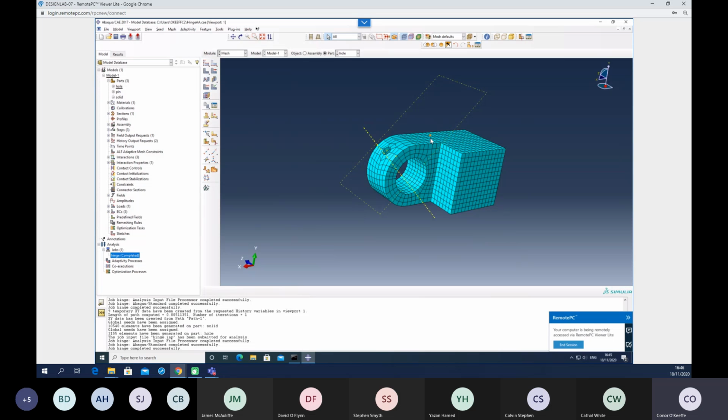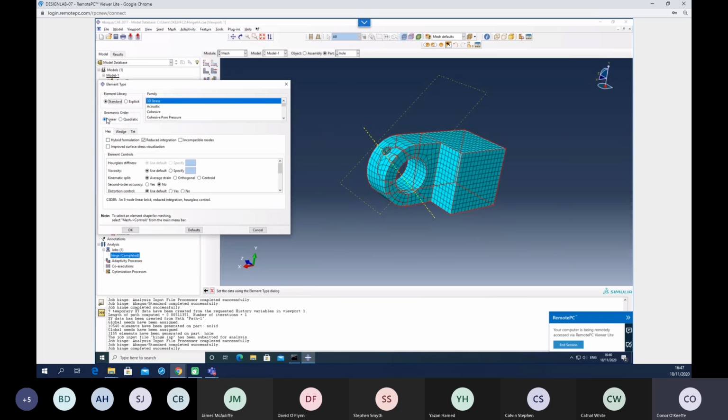The way you want to do that is up to you. If you want to repeat the whole mesh convergence using both element types, or if you want to, with one element type, do your convergence study and then look at one mesh density with 2 different element types or whatever. But obviously, the more work you do, the higher marks you're going to get. And you could also experiment with a few other things here. So you could change the quadratic.